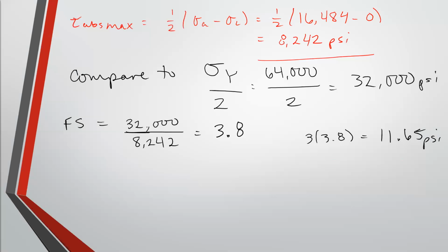Okay, yeah, question. How did you know it was that case to have the sigma absolute max, like it was the sigma A minus sigma C? Because that is the general equation. It's always that case. Because sigma A is always your largest, sigma C is always your smallest principal stress. So therefore, this equation always gives you the radius of the biggest circle. The other options are you can choose between R, sigma 1 over 2 or sigma 2 over 2, and those give you 3 different options, and then you pick the biggest one. But I like this way because this always works. Okay.